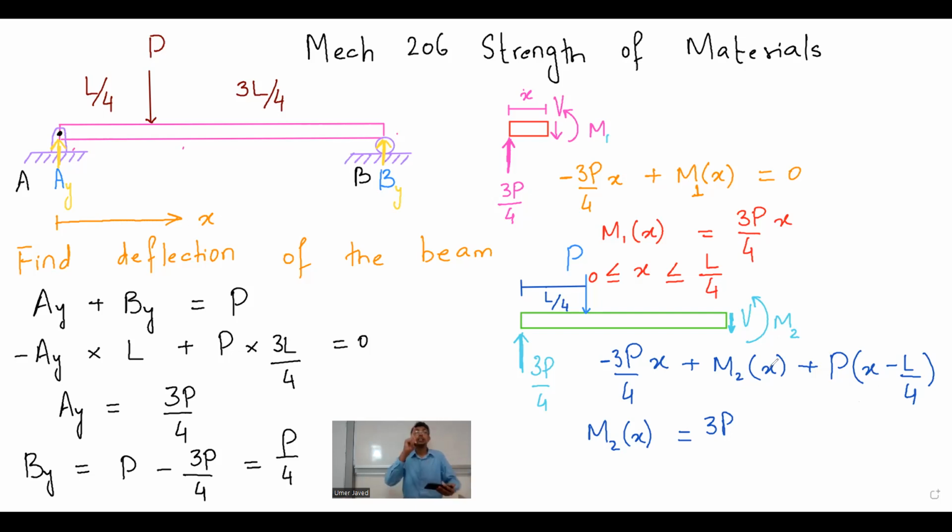What you have to understand is that you are not finding the bending moment at a particular section. You are writing an equation of bending moment for x. Do you remember in your statics, your instructor used to ask you to make a bending moment diagram. So many times you used to write these bending moment equations that have x on the right hand side. What was the purpose of all of those x? So you can find the variation of bending moment for each x. I want such kind of an expression. So now I will answer your question. I took this whole chunk and I put a cut here. When you put a cut here, what is the distance from this point to this cut? X, not L, x. That's why you do x minus L by 4.